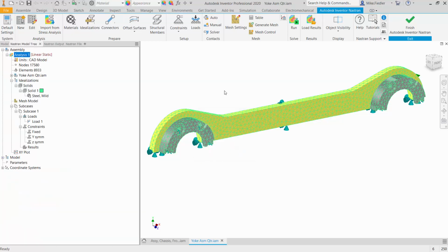The reason for that is because I do have this assembly, right, and I have fixed this component back here, but I don't have any of the other parts fixed. We didn't define any sort of contact. So when I apply the load to the inside circle of the yellow yoke here, what's the relationship of the yellow yoke to the spacer part?